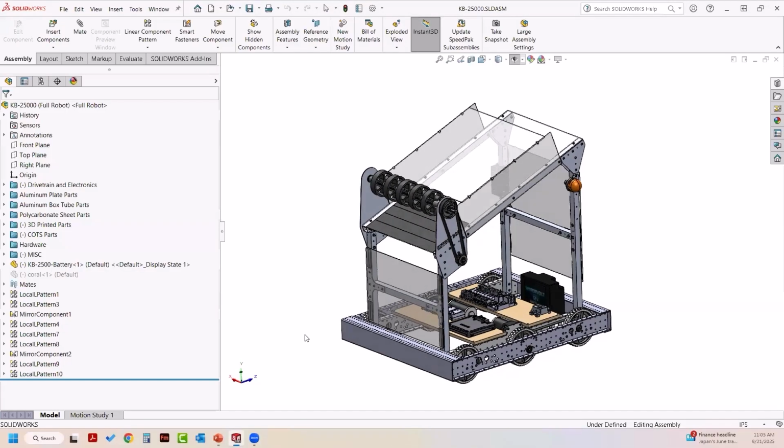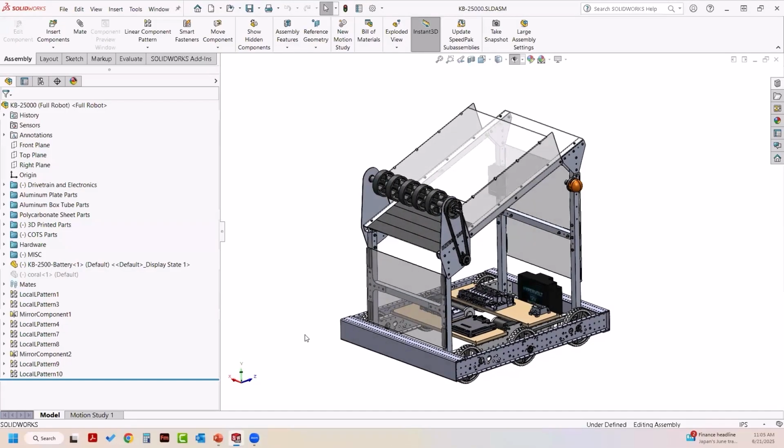Now, when we create simulations, both motion and SolidWorks simulation studies, what we're essentially doing is creating a program that we run, that we execute, and then we look at the results. And just like any other program, you don't write the entire program, click execute, and expect to get anything worthwhile. That's not how that works. What you do is you start out simply, you build it and test it along the way.